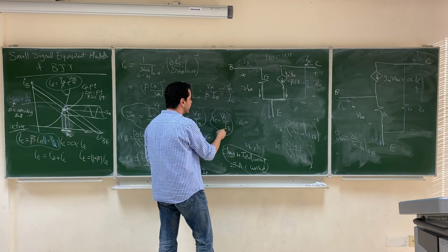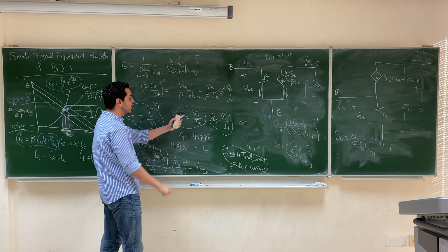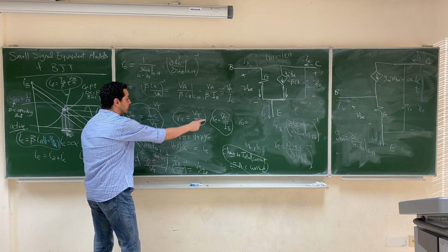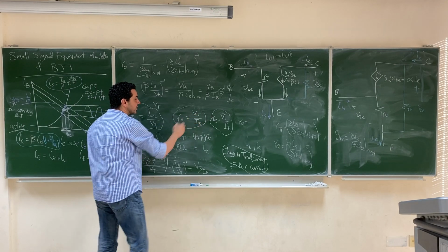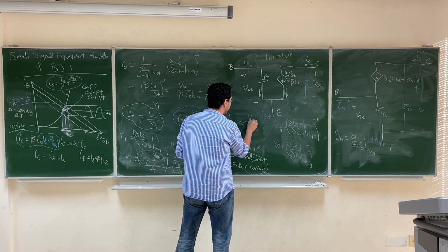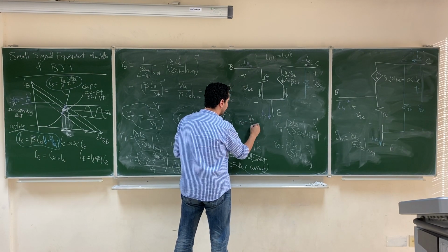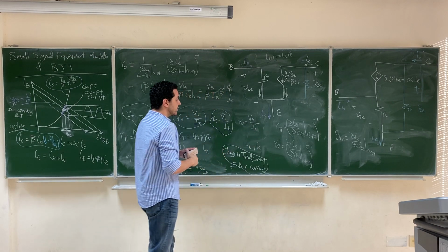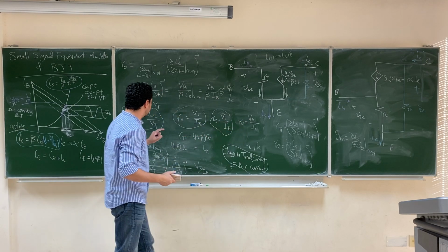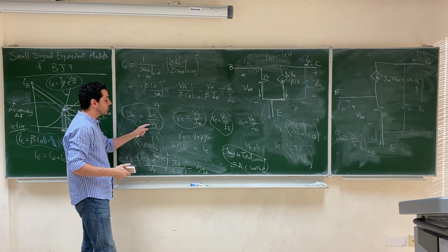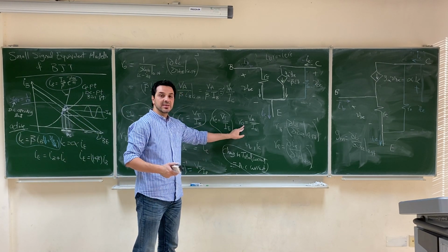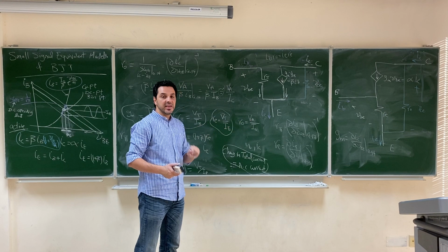since it's a resistance, by the way, all the resistors you will find that they are voltage over current. The conductance, it's a current over voltage. And for all these, we use VT. For the early voltage, because it depends not on VT, it depends on VA, it will be voltage VA over the current of the collector. Again, to make it easy, resistors are voltages over current. Conductance, current over voltage. Always the voltage VT, except for the early effect, the voltage is VA.